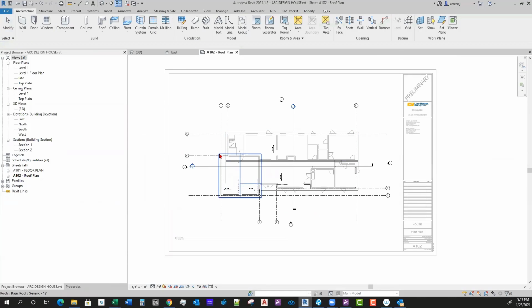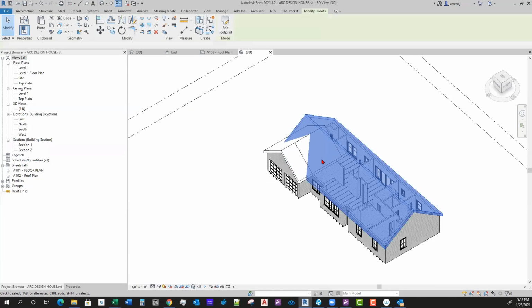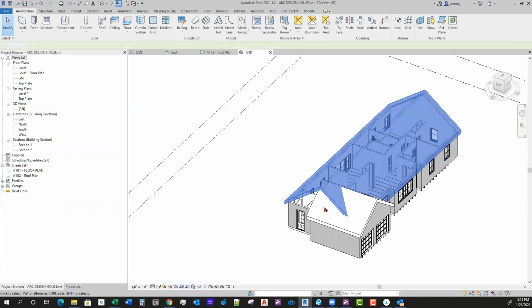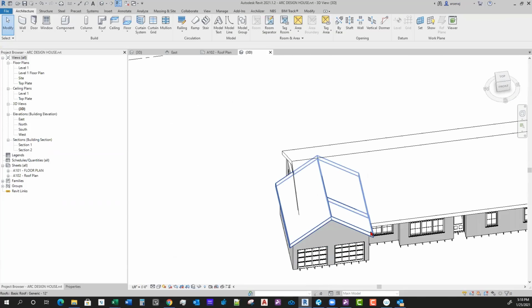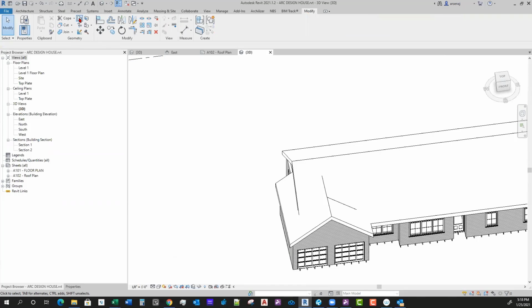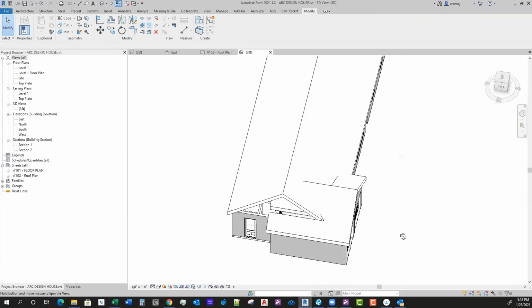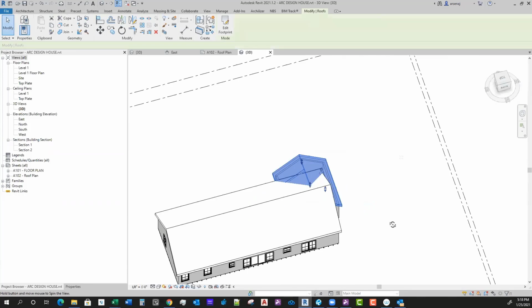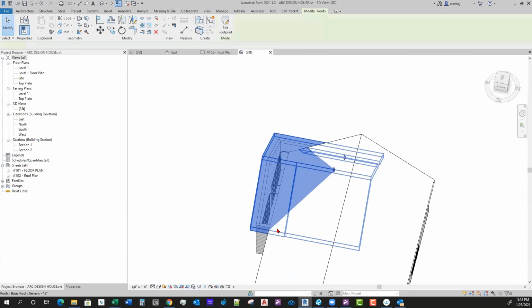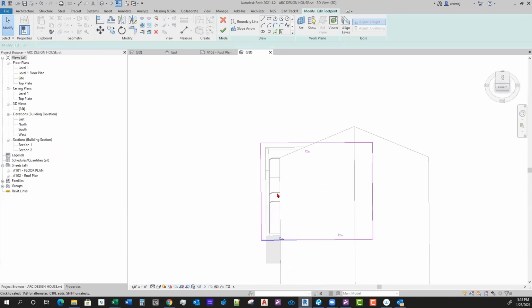So this is the one you were talking about, right? Basically what you were struggling with as far as you had it, you created this as a second roof, and you were saying you're having trouble, right? Because this won't want to join. If you go to join, if you try to click that edge to that edge, it's going to cut it out weird, but it looks like, let's see, what's this other line?